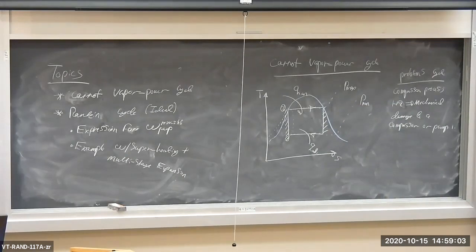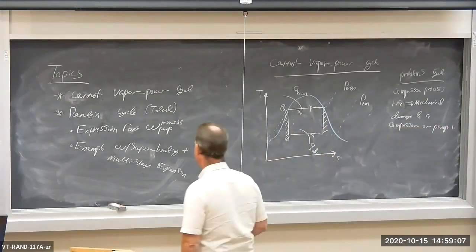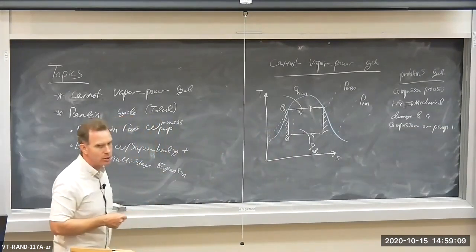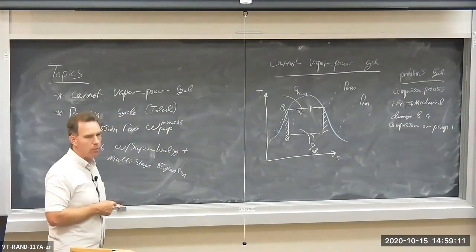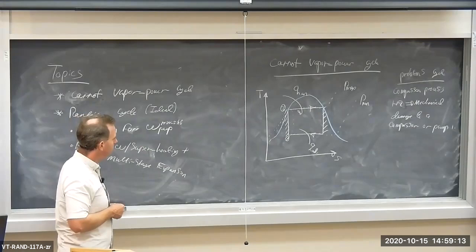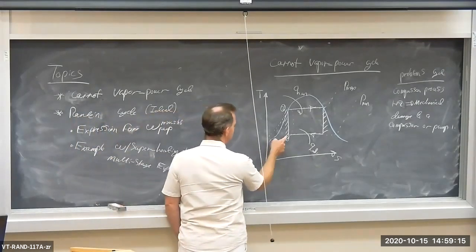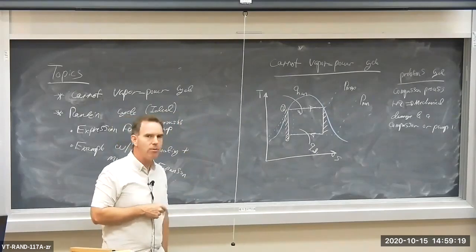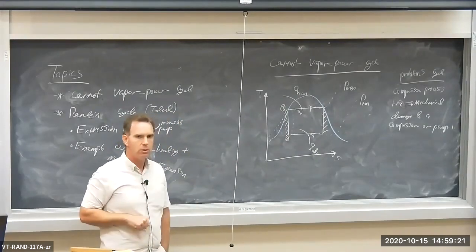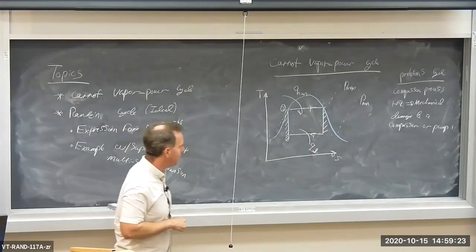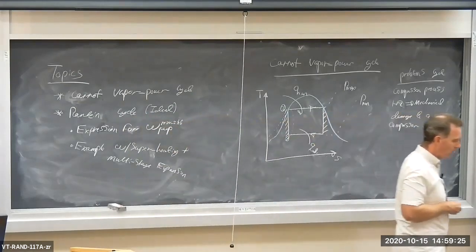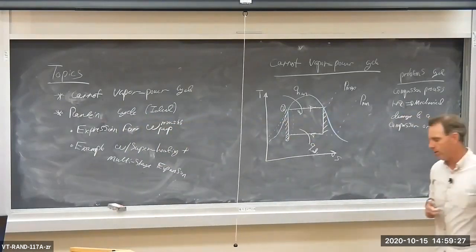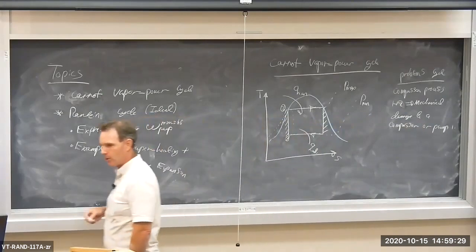So that's the primary objection. There are some other objections here, but they're not so bad. But that's the primary objection to this Carnot cycle within the saturation dome. The process 1 to 2, which is the compression process from P-min to P-max, it's not easy to develop a device which can compress a mixture of liquid and vapor up to a saturated vapor. Not easy to build such a device.